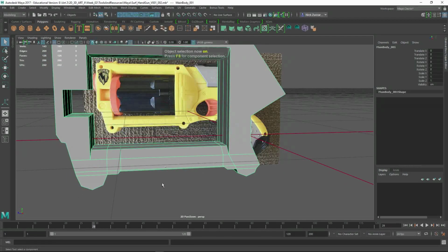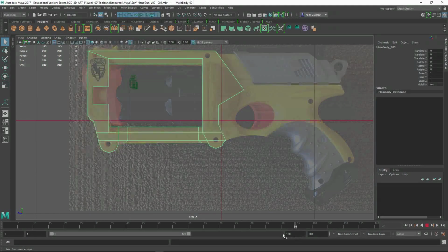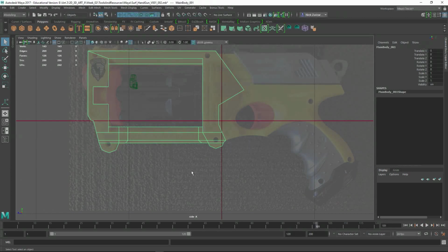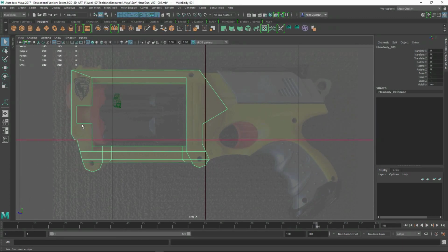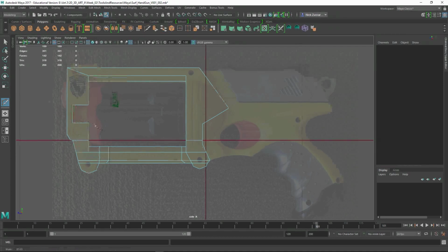So we can use the multi-cut tool, and we could go to the side, and I'm gonna do this a bit so I can see kind of what's going on a little bit more. And shift right click, go to multi-cut tool. I can slice from here, and sometimes if you do this, let me hit backspace, because you can actually drag a line all the way through and just slice through the model, and that comes in pretty handy sometimes. So maybe I just want to slice all the way through this thing like this.